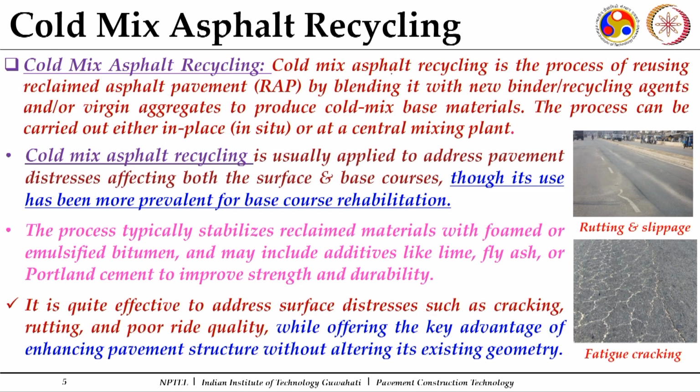Now, as the term itself says, cold mix asphalt recycling is the process of reusing reclaimed asphalt pavement, as in the case of hot mix recycling, by blending it with new binder, recycling agents specifically, or virgin aggregates if required, to produce cold mix for base materials. Most of the time, the recycled mix produced through cold mix recycling is preferred for use as base courses.